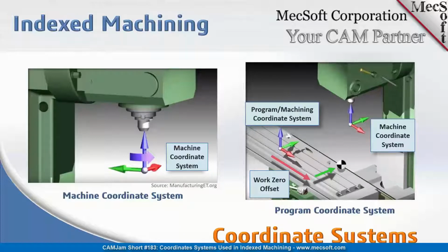Okay, that's fine and dandy in the machine tool system, but how do we translate it to our CAD system? Because we're not working in the machine tool environment. In the CAD system, we have something called the design coordinate system, or what we call the world coordinate system. So we have to match the machine coordinate system with the world coordinate system in the CAD environment. The only requirement, to make things easier for you as a programmer, is to make sure that the world coordinate system is aligned with the machine coordinate system. That's all that is needed. You just need to align it.